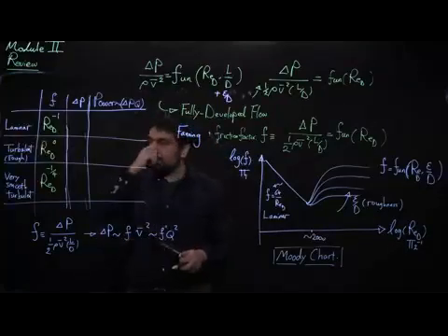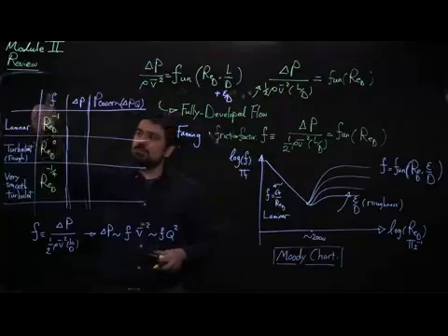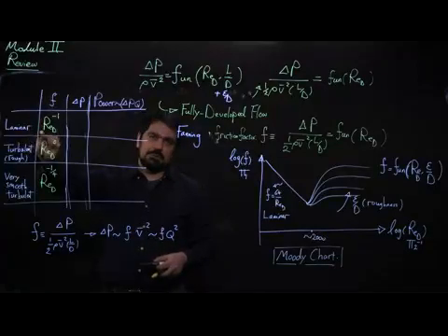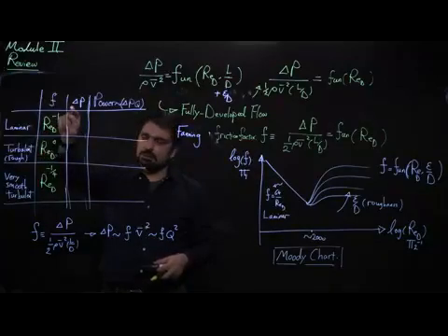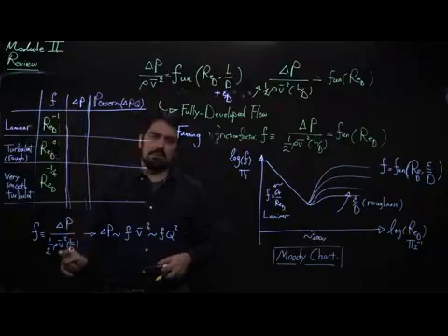So often people will think that the fact that the friction factor is decreasing with Reynolds means that as I go to larger and larger velocities and increase the Reynolds number, I require less pressure. But that's not true, because the friction factor is not only pressure, it's also pressure divided by rho V squared.